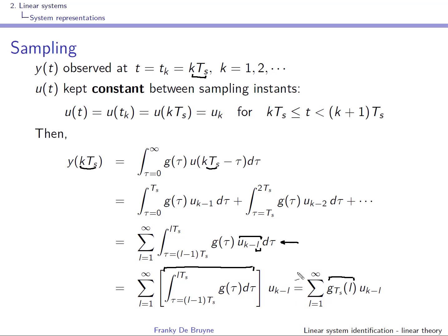So if I write this with the notations of the course of signals and systems, what you'll have is this. y of k is a sum. And here we use the index L, but in the course of signals and systems we had used n, going from 0 to infinity. But if you look at it, n equal to 0 is making a direct relation between u of k and y of k. In most physical systems you will not have this direct link, so this coefficient will be 0 in general.